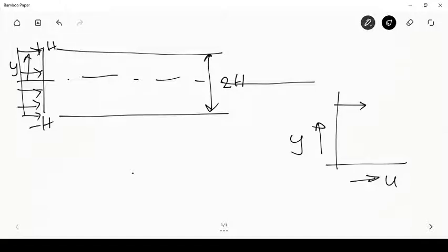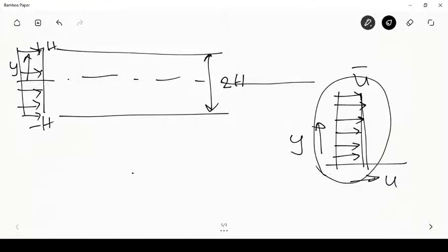So then the velocity at all locations y would be equal at the inlet, okay. So let's say this is a certain velocity called, we can call it as u bar, which is the average velocity over the section. Since the velocity is uniform across the section, the average velocity across the section is also u bar. So since I have now chosen a parallel plates channel into which a flow at a uniform velocity u bar is entering from one end.